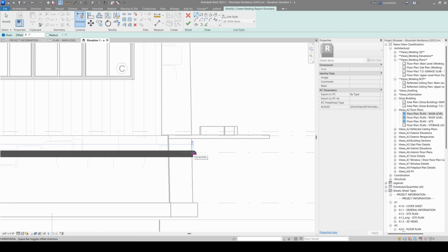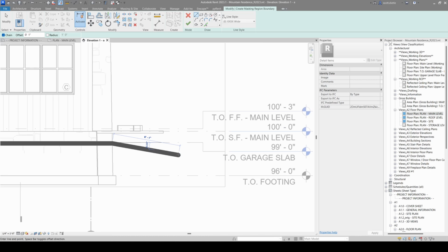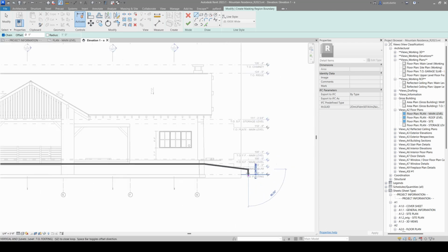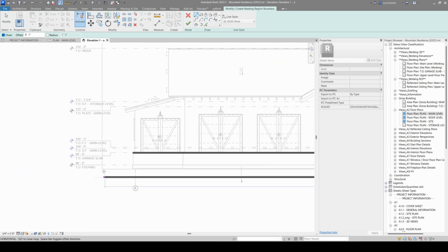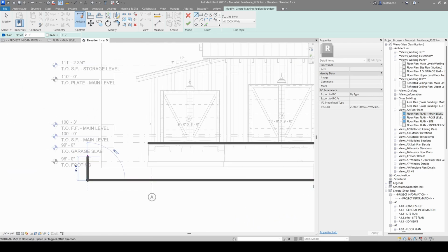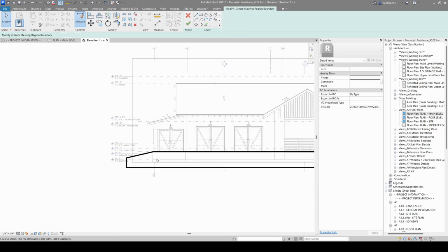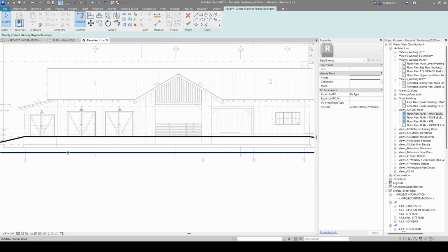And then usually a good rule of thumb is to slope your drainage away from your building at about 5%. That varies based on where you live, but I'm going to take this out beyond the crop region. Okay, I'm going to take it out to here. And then from here, I'm just going to loop back. This will be invisible when my crop is applied. And then slope it again back up to here. So I'm going to make a shape that will mask this out.